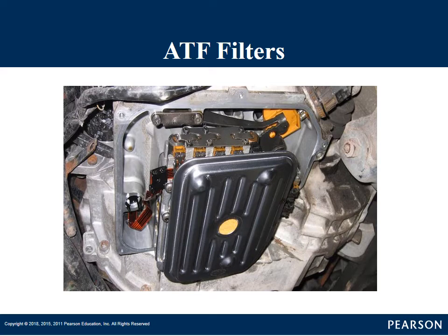There are some spin-on filters. I know Saturn had some spin-on transmission filters. It looked just like an engine oil filter. The Allison in the GM trucks have a spin-on filter. They also have a filter in the pan. The idea was the filter in the pan, the only time you did that was when you were doing repairs. For some reason you had to have the pan off. And the spin-on one was the one that you replaced on regular services.